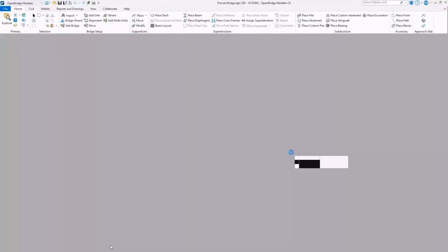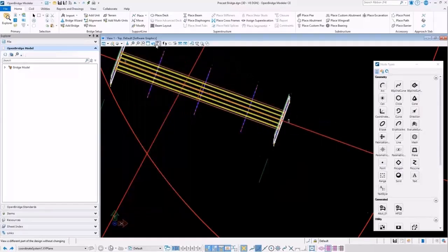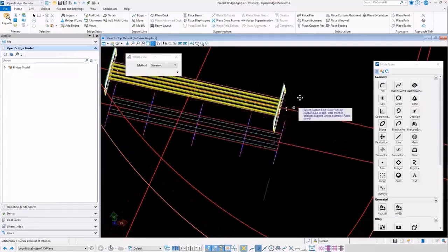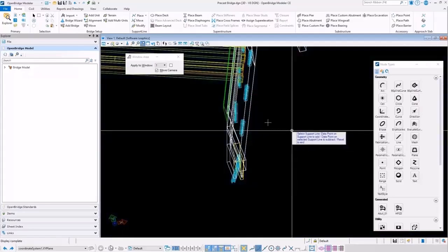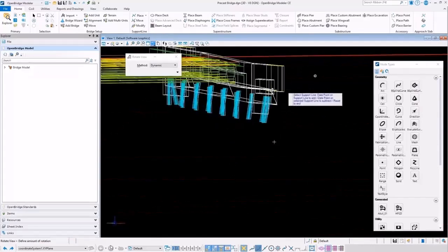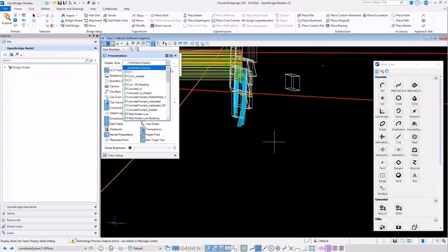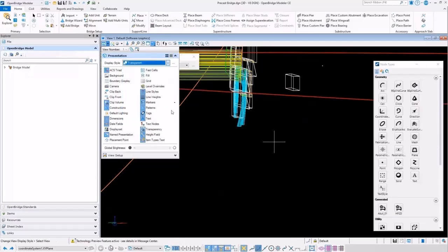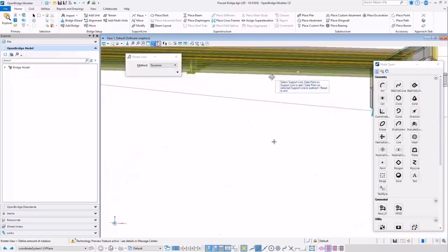Right, so for example, I will place this GC element. Maybe it's not the dimensions that I want, it's all using the defaults. So that's what it has done. I'm going to zoom closer. You can see the complexity could be, for example, that this wing wall has a corner block or a hinge between the back wall and the wing wall itself, so it needs some decision making. If it's a certain angle, I need a certain distance. So the entire abutment in this case is placed.